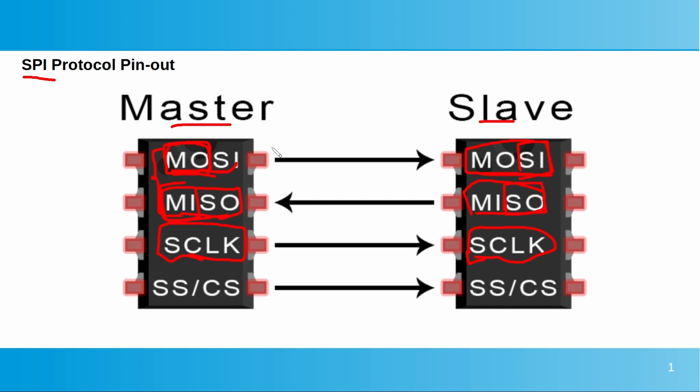This is the reason why we have this direct connection between the MOSI to the MOSI and the MISO to the MISO, because each pin has dual functionalities depending, of course, on whether our SPI is a master or a slave. So for the communication between a master and a slave, we'll have this direct and explicit connection between MOSI to the MOSI and MISO to the MISO.